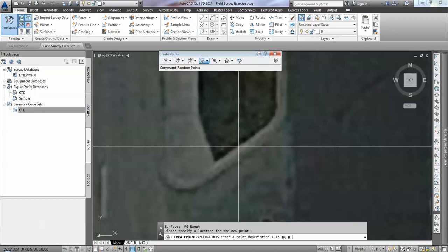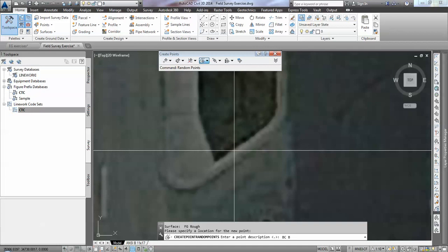So we're shooting along back of curb. We're going to say if we wanted to draw a top face of curb, the flow line, as well as the lip of gutter. So 4 total lines. So the first line, top face of curb. I'm shooting a point right here, and I'm going to start walking this way. So to my left will be the curb. So it'll be a horizontal of negative 0.5. Since there's no change in the vertical, I don't need to put in the vertical offset. The next line will be the flow line, horizontal of negative 0.67, and a vertical of negative 0.5.